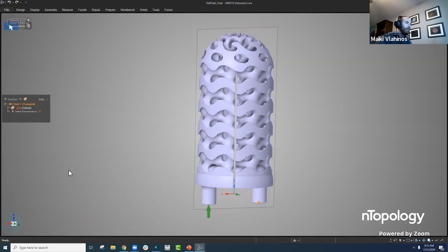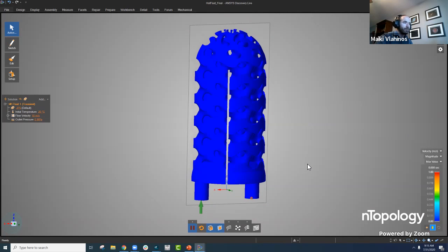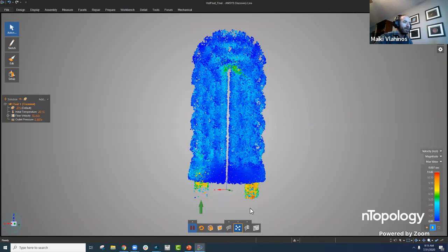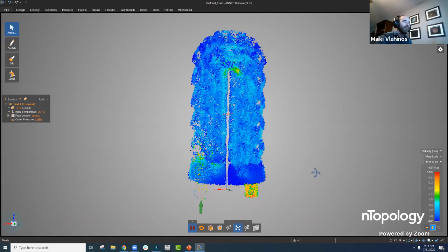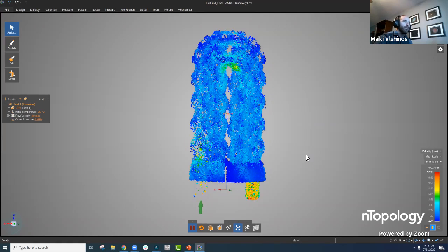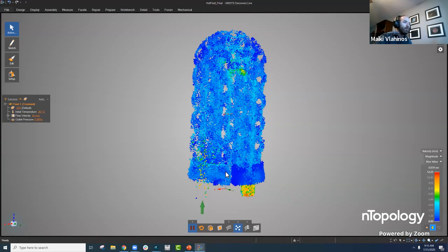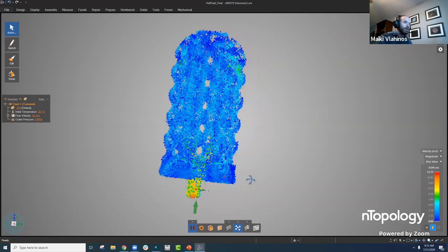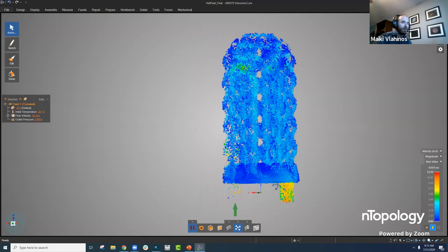And again, we saw that 55% pressure difference. Turn on some particles here. So significant amount more flow, higher velocity, and ultimately we would have more heat transfer coefficient. But looking at the bottom where we have these plenums, there's quite a bit of recirculation, especially when we get to this outlet side over here.